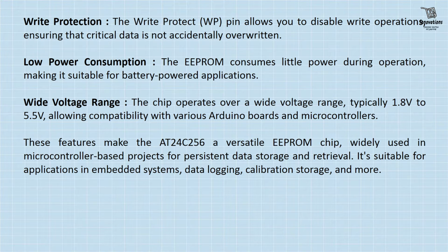The chip operates over a wide voltage range, typically 1.8 volt to 5.5 volt, allowing compatibility with various Arduino boards and microcontrollers. So these features make the AT24C256 a versatile EEPROM chip, widely used in microcontroller-based projects for persistent data storage and retrieval. It's suitable for applications in embedded systems, data logging, calibration storage, and more.